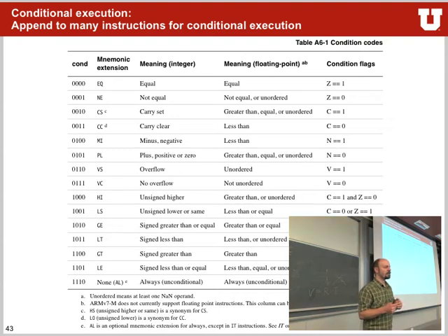If we have, for example, an ADD EQ, this add operation will only be executed if Z is equal to 1 in our code right now. So really handy, right? Instead of having a branch into somewhere where you have this or keep going executing, you can have just this one function as an ADD EQ. Or you can add an NE, CS, or all these different options, which will operate on the different conditional flags in the APSR.